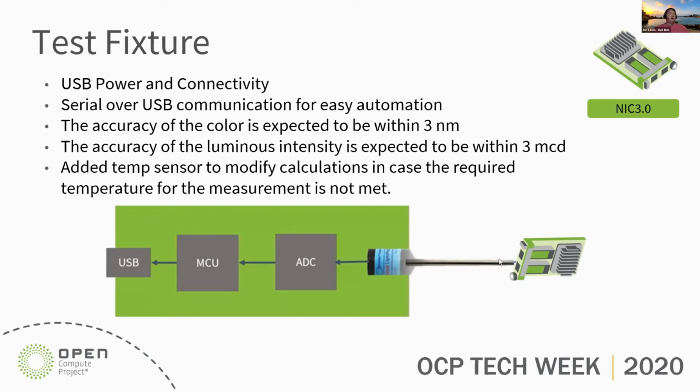We decided to use the Spectre probe that Anatoly and April and others recommended, and simply put an ADC and a micro and go to USB. This is the same MCU used on the existing thermal test fixture. The USB powers the device and the probe, so it's very self-contained.